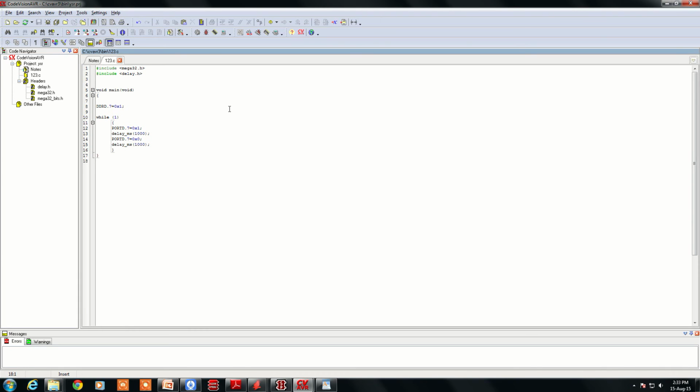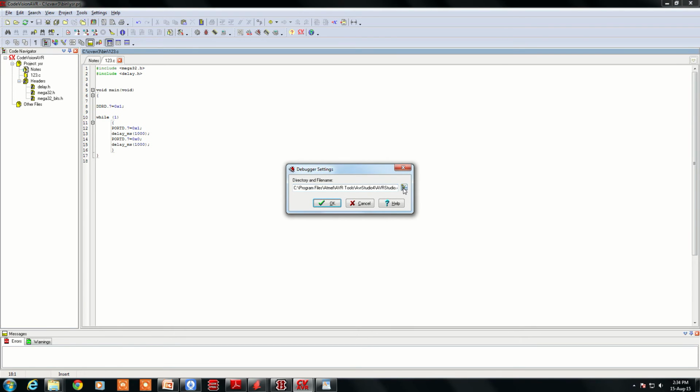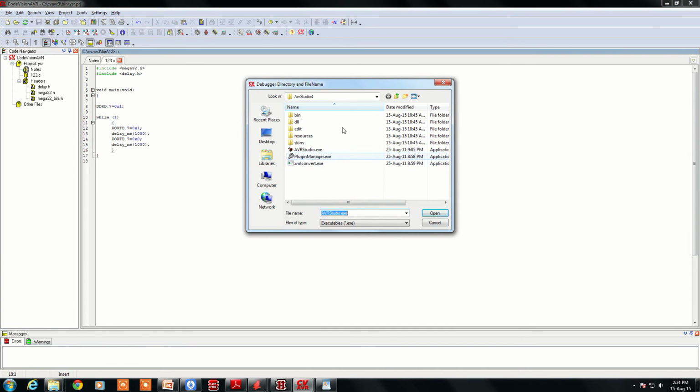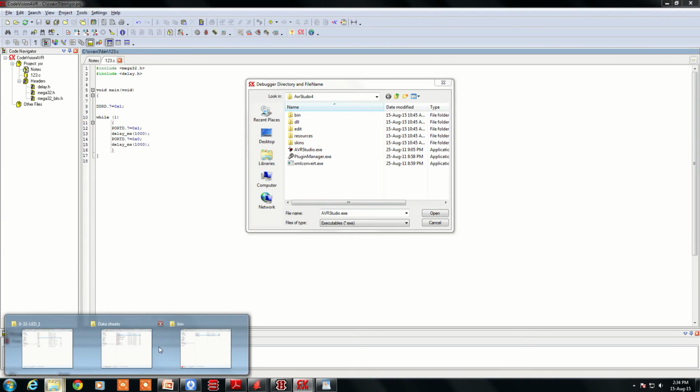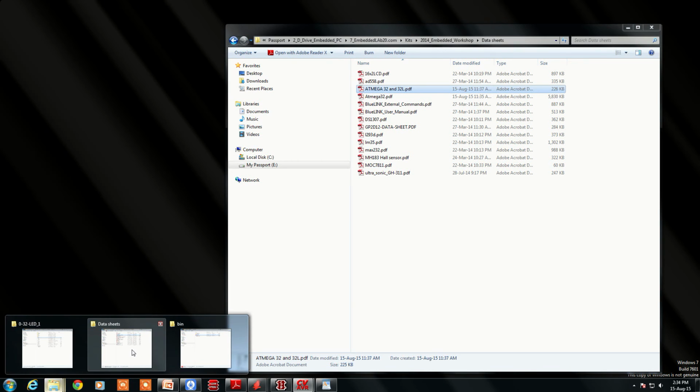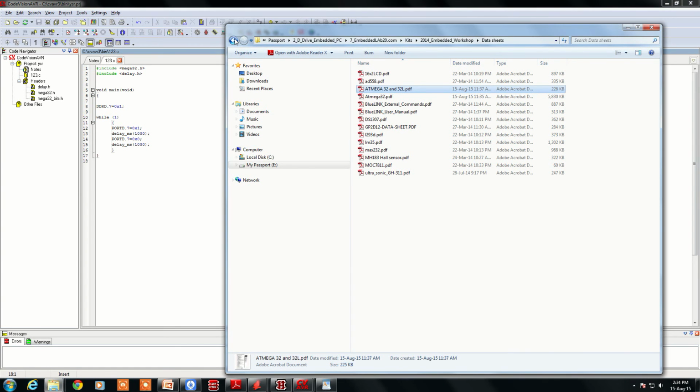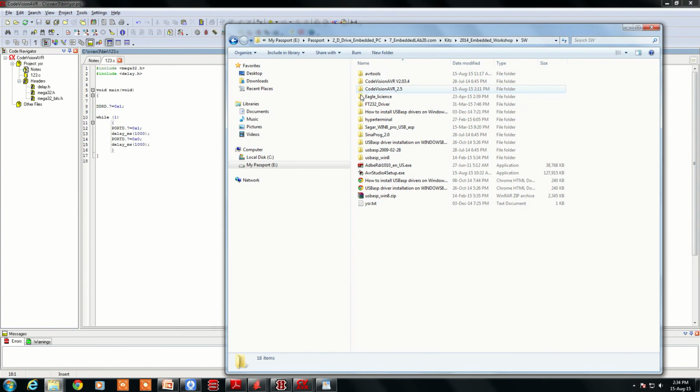This output file, that is the 123.hex file you have created, we want to burn on the chip. But if you want to simulate it, since you have installed CodeVision for the first time, go to settings, and in debugger you select the debugger name. The debugger is the same thing you have installed, in your software folder. There is a tool called AVR Studio 4.